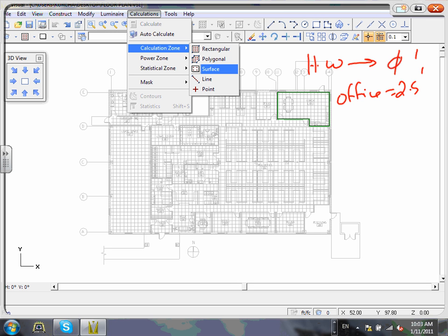In any other office, any other area, even the bathroom, guys, you're usually sitting or standing in front of the sink or something. You need it to be at 2.5. Somebody can argue in the bathroom you might need it at 0, but let's just standardize, guys. If you put it at 0 in the bathroom, you'll hurt my feelings. What I suggest: everything at 2.5 feet, hallway at 0.